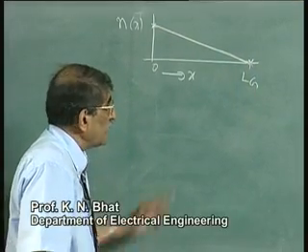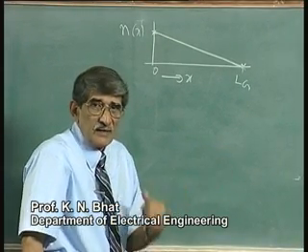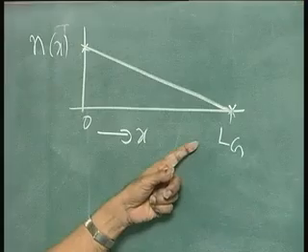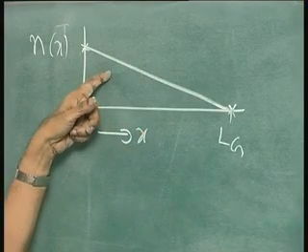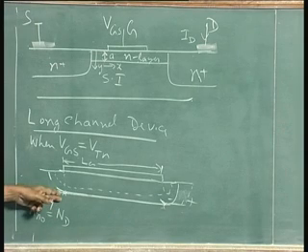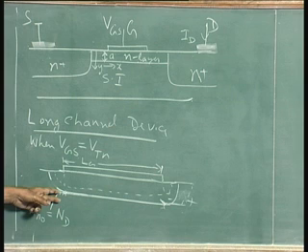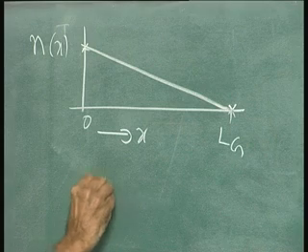So, when Vg is equal to Vtn, there is a concentration gradient. How much the current is would depend upon how much the area of cross section is. Area of cross section is very small, so that is a very thin layer, maybe a couple of Debye lengths corresponding to kT by q into 2 or something like that, very small voltage, very small thickness. So, current density may be there, but current will be small. So, the ID in this case will be